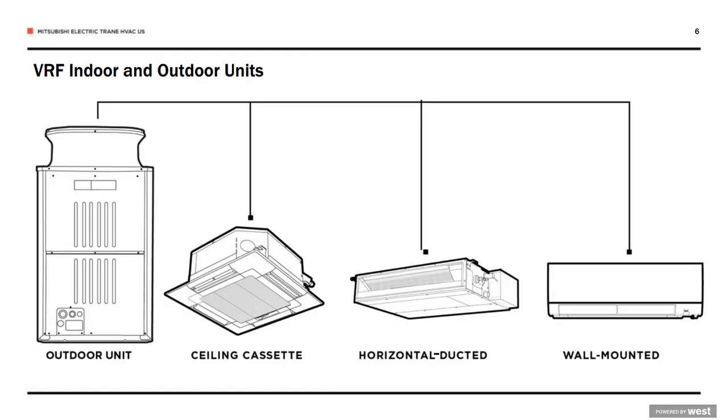At its most basic, a VRF system consists of an outdoor unit connected to a network of indoor units through refrigerant piping, as we discussed a minute ago. The system's operation is governed by a network of controls, which read data from a variety of sensors located throughout the system. VRF systems can be applied in 2 basic configurations: air source and water source.